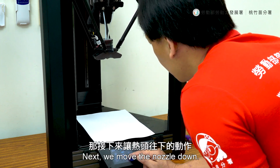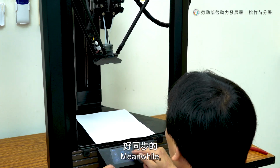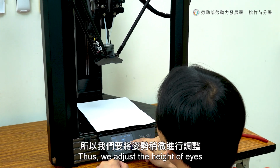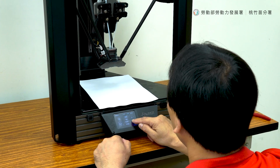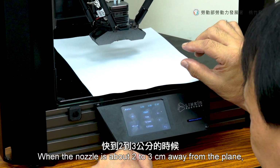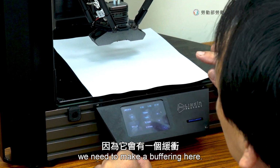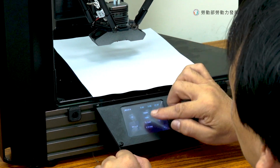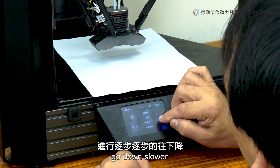Next, we move the nozzle down. Okay, 10 mm down once. We gradually move it. Meanwhile, our eyes are set horizontally aligned with the height of the nozzle. Thus, we adjust the height of the eyes so we can see the nozzle. When the nozzle is about 2 to 3 centimeters away from the plane, we need to make a buffering here, so we'll slow it down. Switching the moving distance to a smaller scale is safer. We change from 10 into 1 millimeter, making it go down slower.